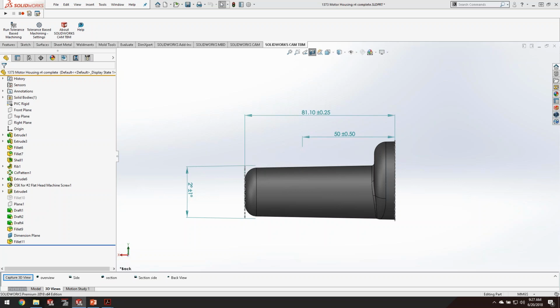So in MBD, there should be less ambiguity, right? If we're looking at a specific section, it's part of the 3D model. We don't have to reference back to an original or see what the approximate location is. If we're looking at a detail view or section view, we're just taking that CAD model and actually sectioning it out. And then we can use the different aspects of that 3D model to start to dig into it a little bit more deeply.